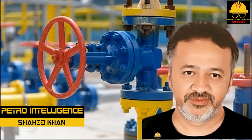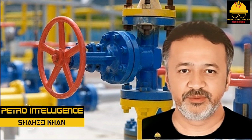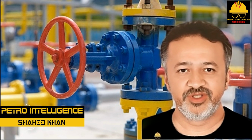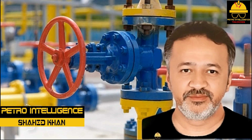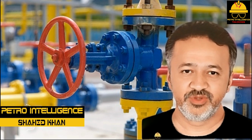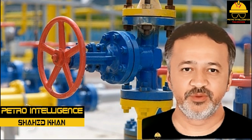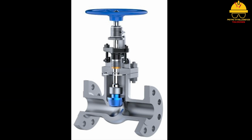The bronze globe valve is used in low pressure and low temperature systems. The brass globe valve is used in low pressure and low temperature. The cast iron globe valve is used in water lubrication and some low pressure steam systems. When compared to gate valves, globe valves as shown in picture have a much greater pressure drop across the valve.